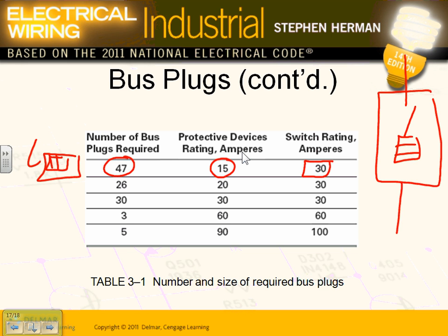So this I have, right? And this is 30, this is, what is it, 15 amp? 15 amp fuse, this is 30 amp disconnect. This assembly, a disconnect and fuse, I have 47 of them in our project. These are the ones that you're looking at right here. These little machines here, these little disconnects, 47 of them. And you can imagine, I'm going to go all the way to this 90 amp, and they're sitting in a 100 disconnect. 100 disconnect, 90 amps. Remember the disconnects 30, 60, 100, multiples of hundreds for the most part, and overcurrent protection device based on the code.